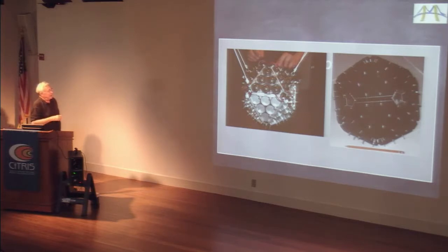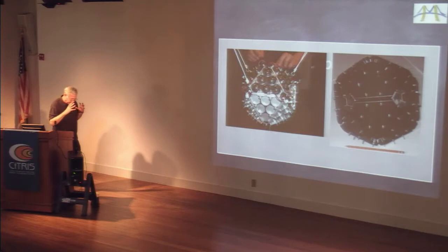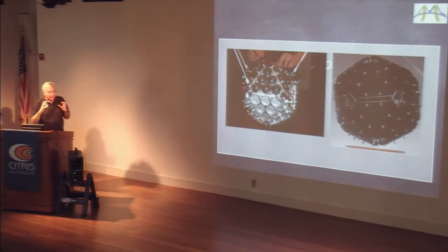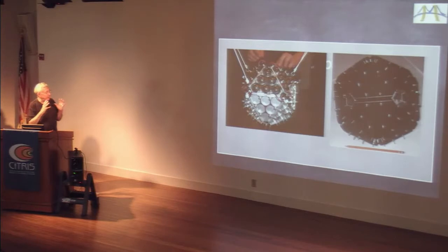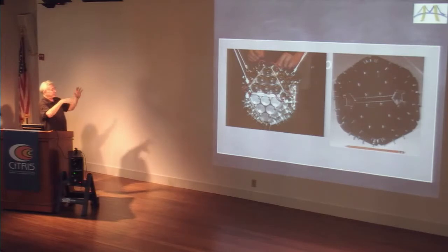So we end up with a fairly large channel count to handle here. One of the goals of this particular speaker was to allow us to control, in real time, of course, the radiation patterns. We used a spherical harmonic representation for that, and we primarily worked with beams that we formed from this. Then we would move the beams associated with different voices. Our idea was to make the electroacoustic source behave in some sense like a traditional musical instrument that radiates in a very different way depending on what notes are being played.